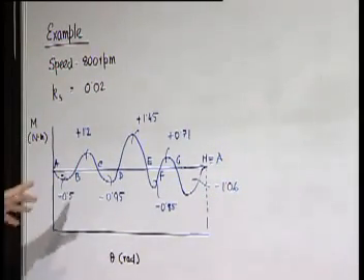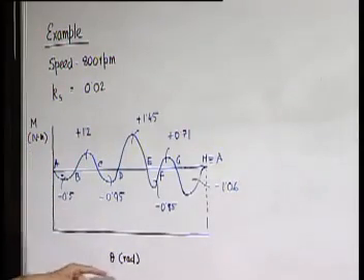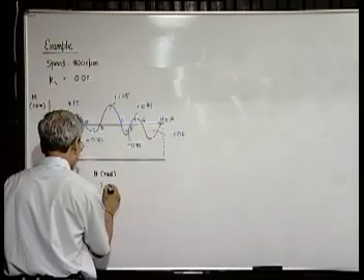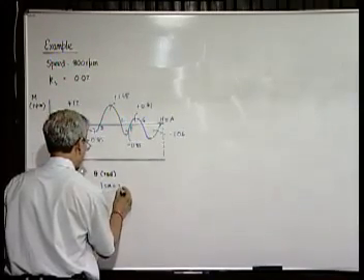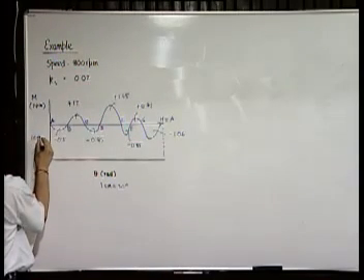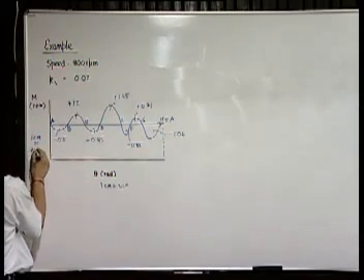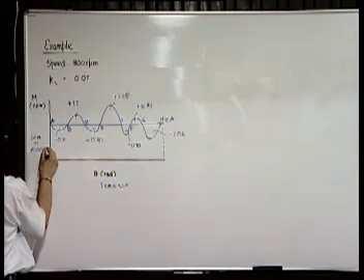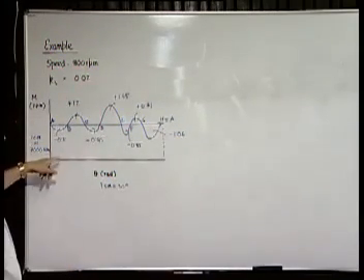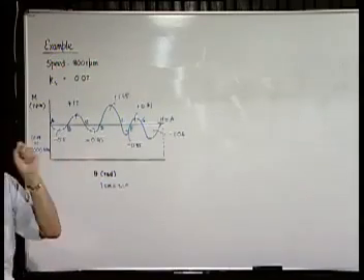So we plot this. That means here actually the scale will be 1 centimeter is equal to 30 degrees, and here 1 centimeter will be equivalent to 7,000 Newton meter. That is the scale we have used, and using these scales, these are the areas we measure by planimeter.